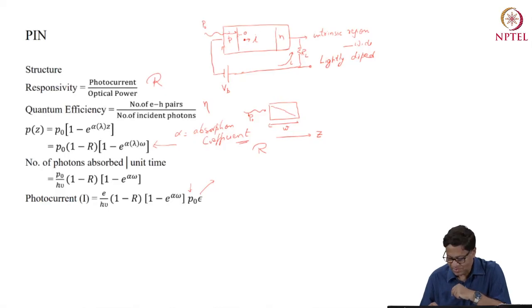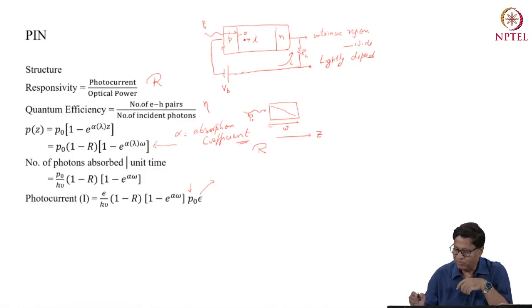It basically tells you what proportion of photons is converted into electron-hole pairs. Ideally epsilon should be 1, so that all the photons result in electron-hole pairs, but in practice that doesn't happen, so epsilon will be less than 1. So you have to multiply by it, and the photocurrent which flows through the load resistor is a function of this epsilon.